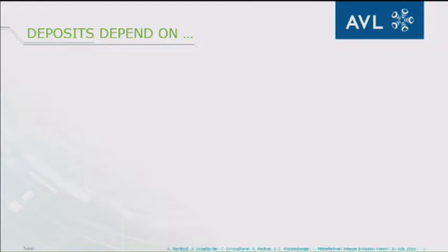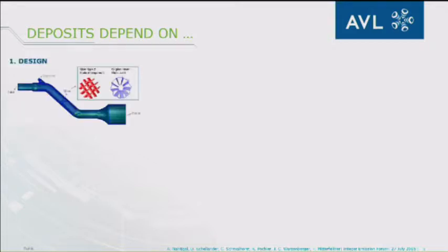Deposits depend on several influencing factors. One is the design. The location of the urea injector is not irrelevant. What is the distance between the injection point and the mixing device, or the distance to the catalyst?